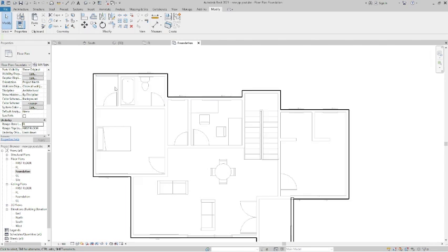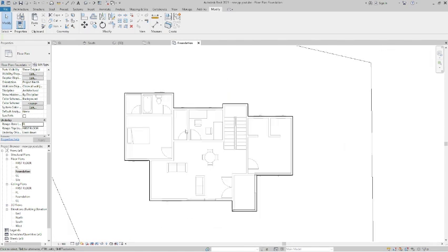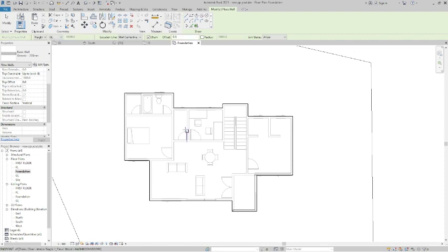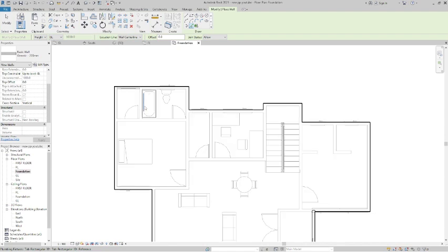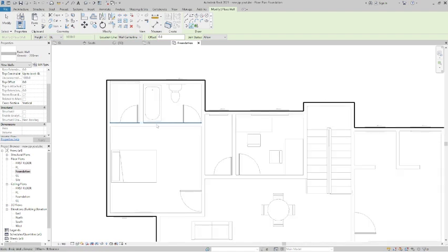So you can see that you have your lines here. Then I'll choose my wall, WA on the keyboard. Choose the pick lines. So the foundation, I'm going to click here, but then I have to check the base constraint. This foundation, then the top is supposed to be at what? Final floor.